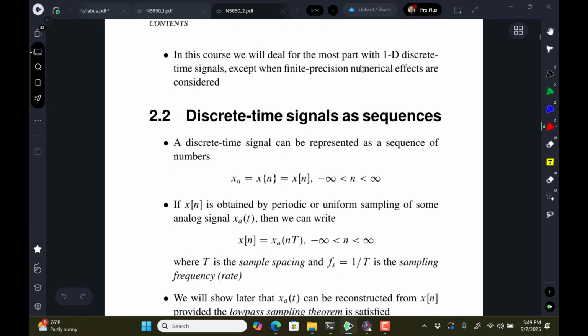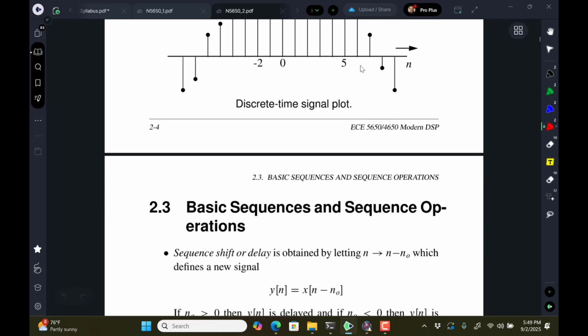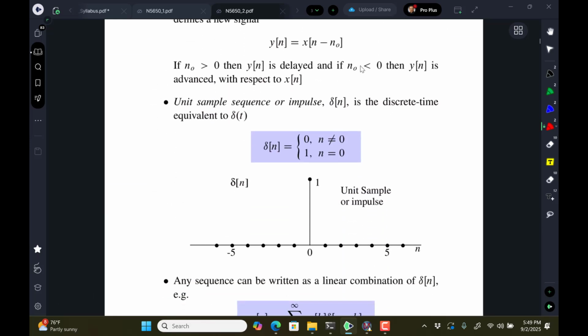So last week when I was taking us down, we were looking at the unit impulse function right here, and we were also looking at delaying by an arbitrary amount. Anytime we have a sequence and we want to shift it to the right, we put in a minus some positive number. If we want to shift it to the left, we add a positive number. And the way I always get at that, like for this function down here, if you had